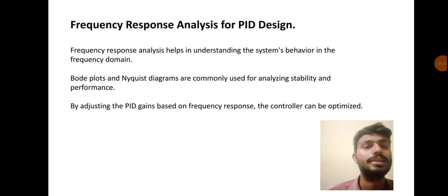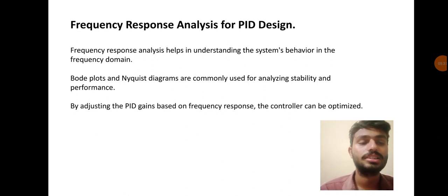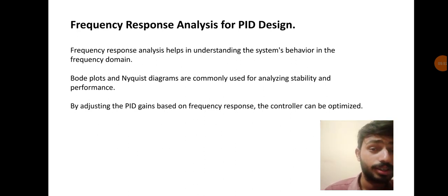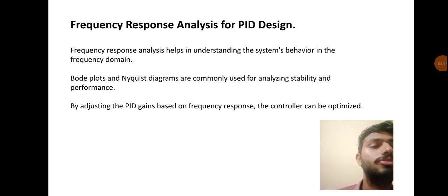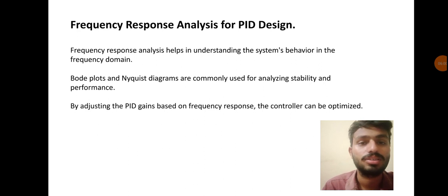Frequency response analysis for PID design. Frequency response analysis helps in understanding the system's behavior in the frequency domain. Bode plots and Nyquist diagrams are commonly used for analyzing stability and performance. By adjusting the PID gains based on frequency response, the controller can be optimized easily.